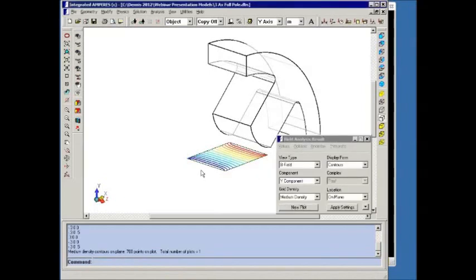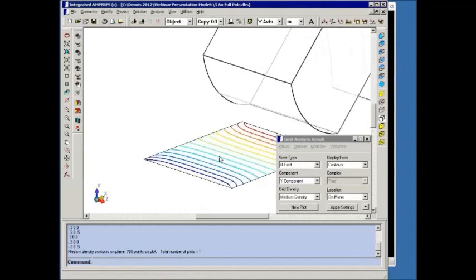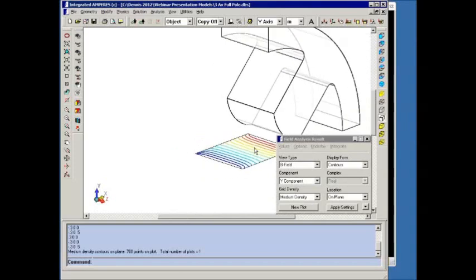So you can see that in the middle of the air gap there's a nice gradient of the field, which is basically the way quadrupole magnets are designed to function. Now you notice that I had to specify the corner points of the plane. We could also just pick a surface for plotting. And one of the key techniques, which is very useful and simplifies your work when you're doing three-dimensional plots, is